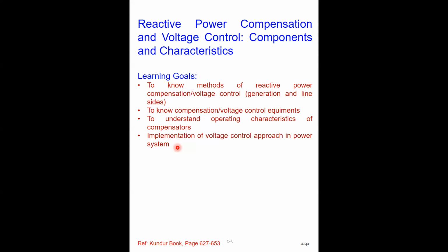It is said now that since we have a high amount of renewable integration in the system, mainly at the distribution network, the policy framework has come into existence, and it says that smart inverters which we use in the PV system should in some way contribute towards reactive power compensation or the voltage improvement at the distribution network.